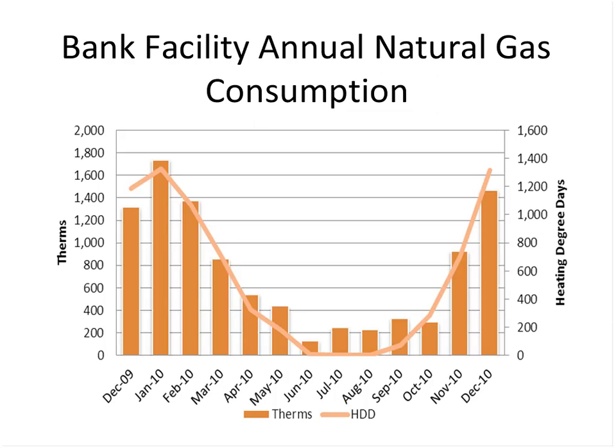There might be. We've seen buildings that use 80% as much gas in the summertime as they do in the wintertime, and we knew there was a big problem with reheating that building. So looking at these graphs gives you an idea, and I'd say heating looks to be fairly normal in this building.